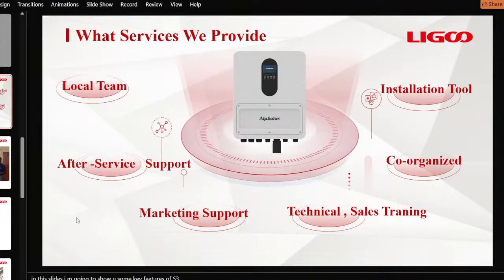And also 1.5 times grid input over-provisioning technology from 40 to 60 volts. You know how much that is to give to some certain loads that at a point get to those ranges. Now we have the minimum MPPT operating voltage going from 60 volts. As early as 7 or 8, your inverter has kicked up and it has started charging and also feeding the house. And even when you are getting late in the evening, around 6 to 7, it is still also generating a little bit to meet up.